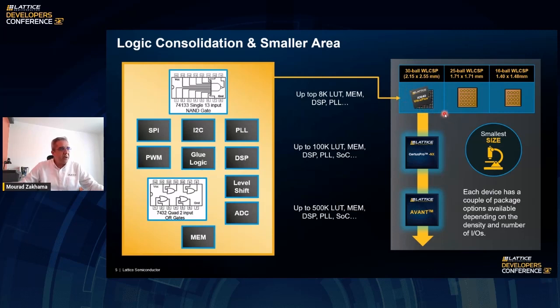It's a 2.1 by 2.5 millimeter device and can integrate up to 500,000 logic cells. So we're going to see this terminology later, but that's a lot of logic that integrates multiple of these components in the same device. This is a device that is offered, for instance, in multiple packages. So it depends on your needs for your board or the PCB technology that you are using.